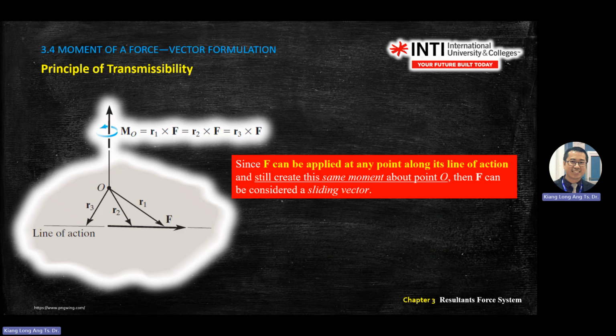Okay, so this is to highlight the force you must maintain at the line of action. Then your moment won't be changing. You fix the line of action and where you stand, or the focus point. Then you're still creating the moment. This is called the principle of transmissibility. Means you can move the force front and back.